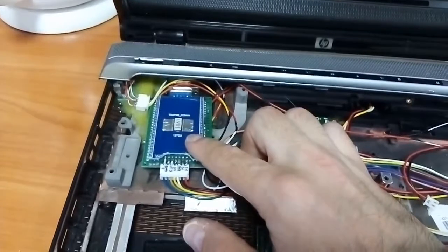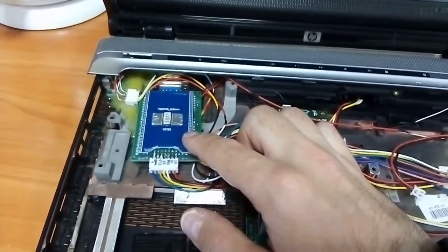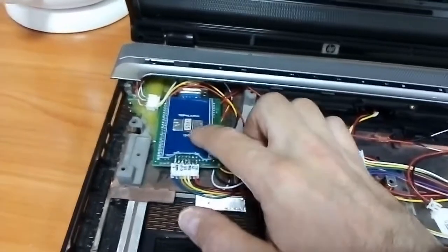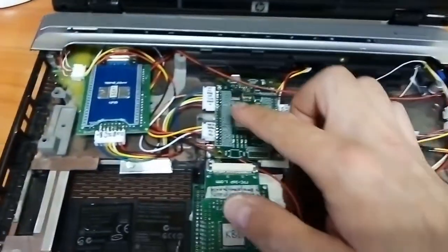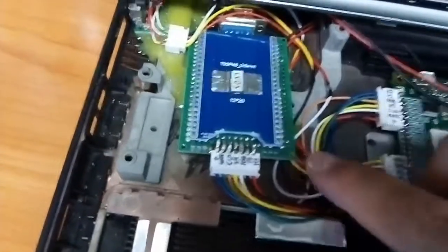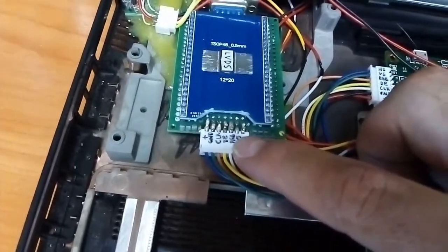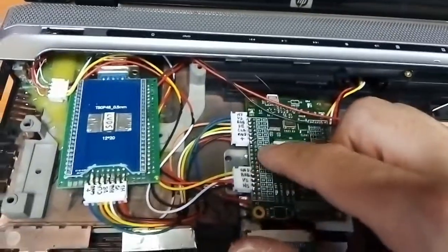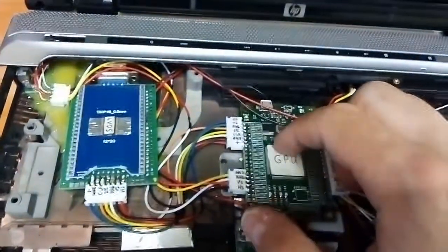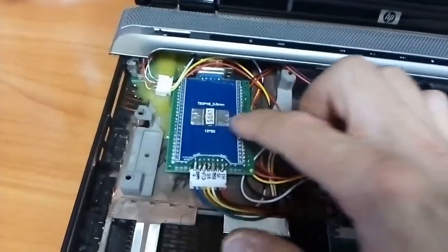This LVDS runs at pretty high frequency. That's over 200 megahertz, and I assigned this job to this controller to prepare, to cook this signal, and I gave it the required components: horizontal sync, vertical sync, that's the pixel channel drawing, RGB, device enabled, it needs this signal, clock, ground, and plus. The clock runs from here at 68 megahertz. It's okay for it, it can do over 200, but let it make it.